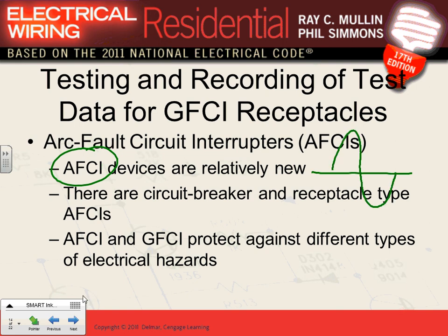Now, say Brian abused an extension cord plugged into one of his outlets, really abused it, moving the couch and dropping it right on top of the cord, so it's frayed, and it starts arcing. When it arcs, instead of the sinusoidal wave looking like this, this is how you're going to see it. The signal will look something like this.